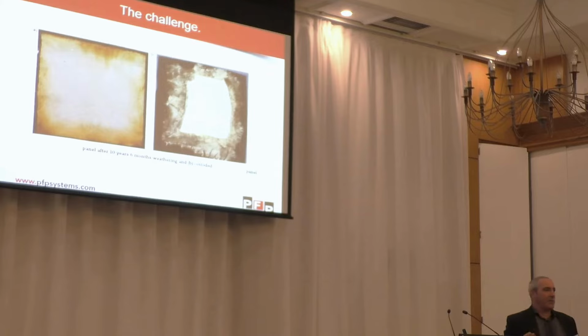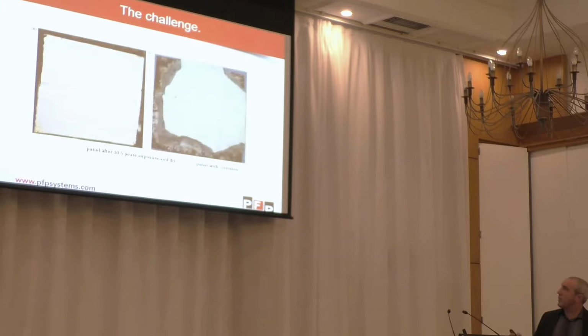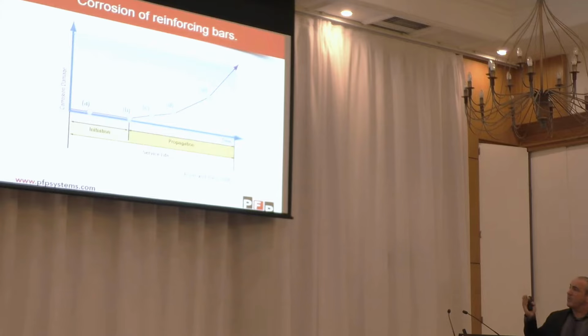And I think all I wanted to emphasise here is that what happens underneath actually has an effect on the performance. So this and the next one as well, these were tests done in a laboratory a couple of years ago where they established that managing the corrosion under the passive fireproofing is critical for the performance of the fireproofing itself. And that's really the point I'm trying to get across. What we want to prevent is moving the corrosion beyond point B. So in corrosion under reinforcing bars, for example, this is the closest model I could find for that propagation of corrosion in a cementitious environment.